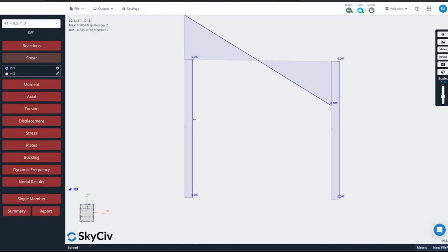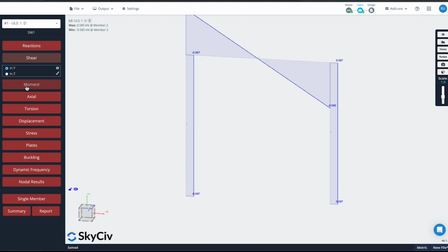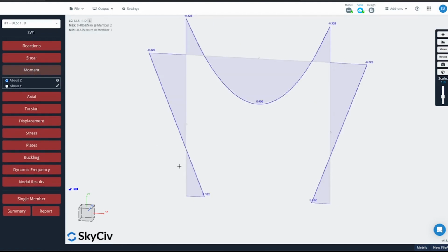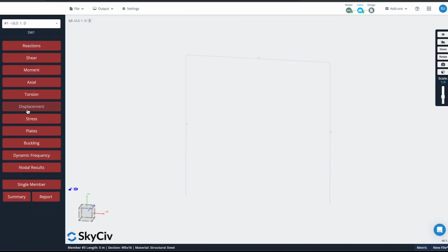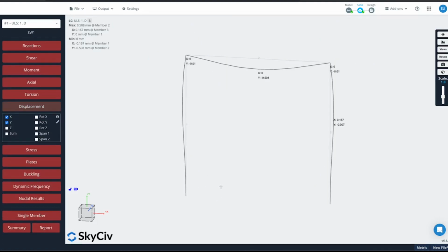So we can see here, this is just like the typical reactions you'd expect from a moment frame. It's coming here, this is kind of a neutral point, comes here. We're seeing just some bending here and then bending there. If you want to actually see the displacement, you can see how it's under stress. So the weight's coming down from here, slightly buckling here, but you can see since this point and these points are fixed, there's actually something keeping them in place there.